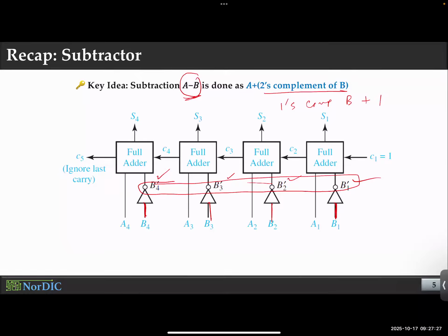We were even planning to use a half adder there so that there is no option to even provide any carry. Okay, hold on a second. Instead of doing so, if I use a full adder and make the first carry 1, that will be like adding 1 to the 1's complement of b, don't you think? And that will convert it to the 2's complement of b. And apparently this adder will behave like a subtractor, essentially. So I hope when you see a circuit with the first carry being 1, the first thing that pops up in your head is, oh, it's a subtractor.